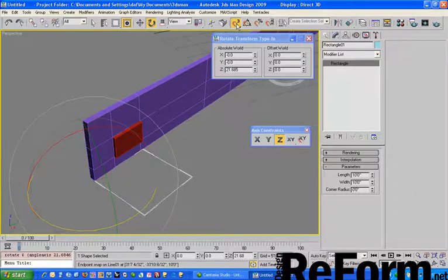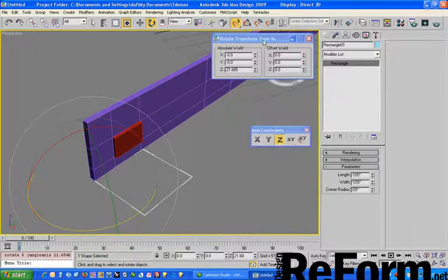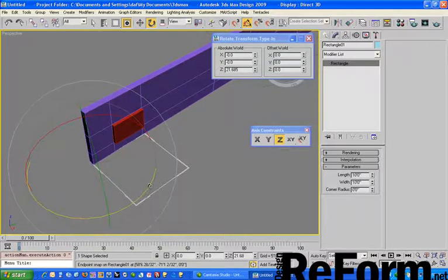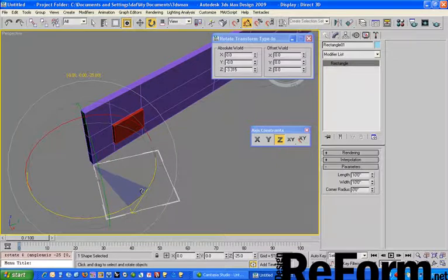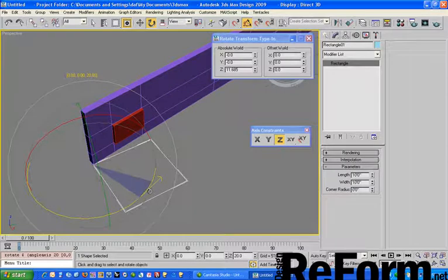So the last thing about snapping I want to show, if I go over here to the options, is angle snaps, because I use those quite a bit. And here the increment is set to 5, so you turn that on here. I'll hit regular S to turn that off. Now you can see up here in the yellow above my gizmo that I'm snapping with angles, and the keyboard shortcut for that is A. So with it off, see it, it's on right now and it's snapping in 5-degree increments. If I turn that off, I can kind of do